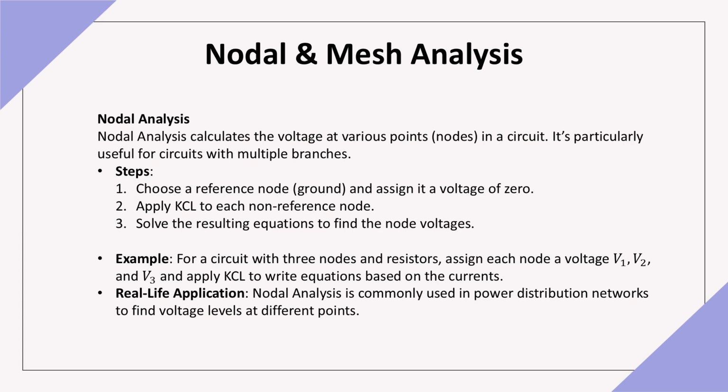Nodal analysis is a systematic method for finding voltages at various points in a circuit. The process involves 3 key steps. Choose a reference node, ground, with 0 voltage. Apply KCL to each non-reference node. Solve the resulting equations. This technique is particularly valuable when analyzing circuits with multiple branches and voltage sources, such as in power distribution networks.